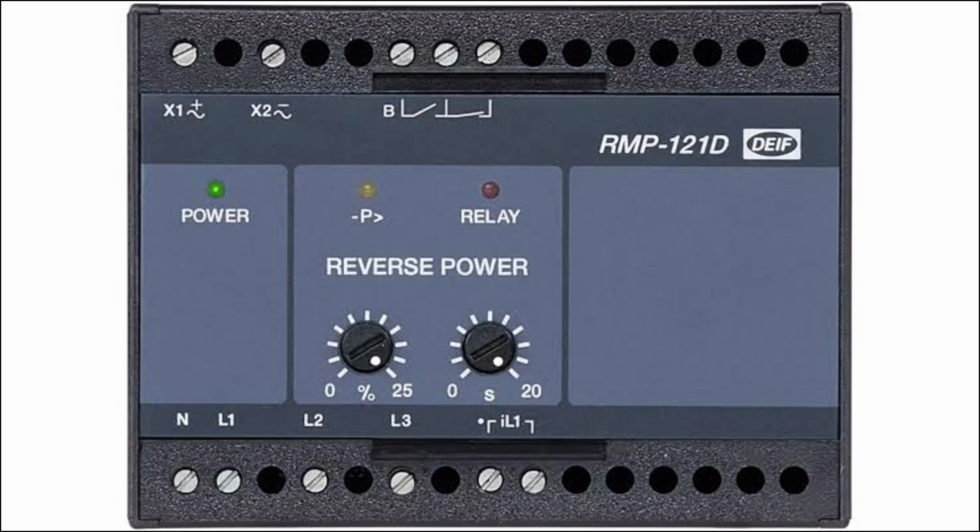Most reverse power relays have adjustable settings to allow the customer to do the setting according to the installed equipment. The trip point is usually adjusted to between 2 to 20% of the input current, while the time delay is adjusted from 0 to 20 seconds. A 5-second time delay is often used to avoid tripping the circuit during synchronization. In most practical applications, the reverse power settings are between 8 to 15% for diesel engines and between 2 to 6% for turbine prime movers.